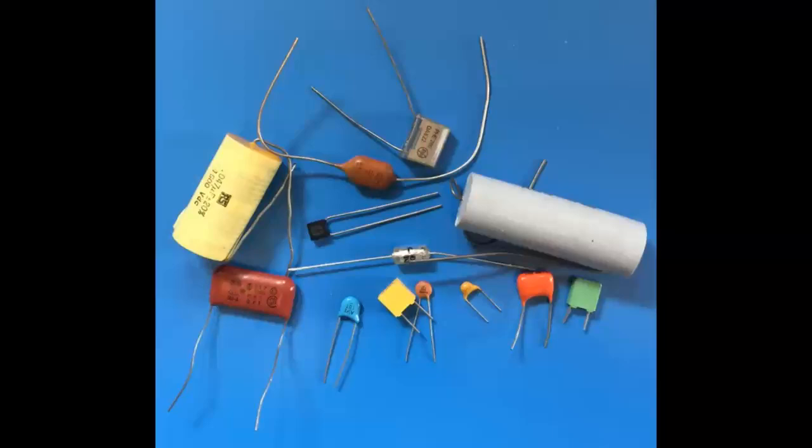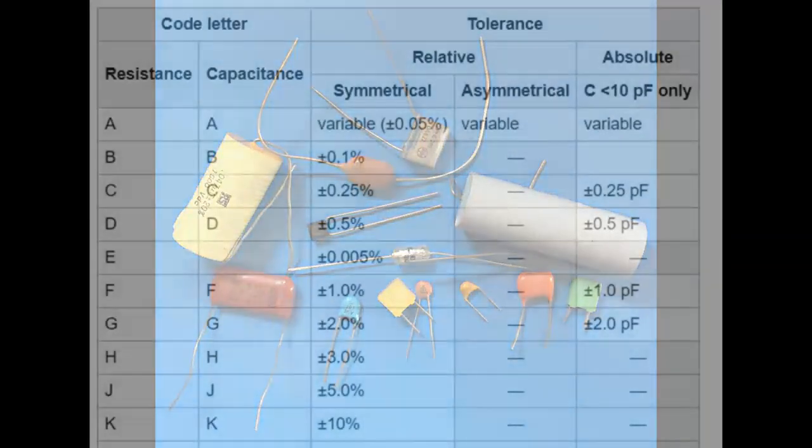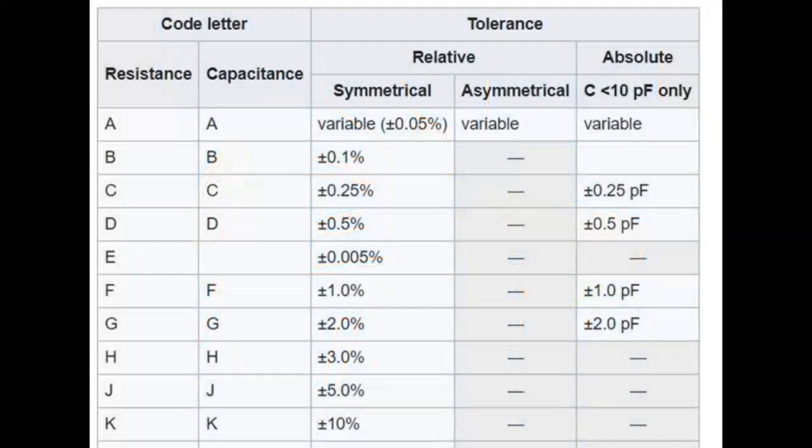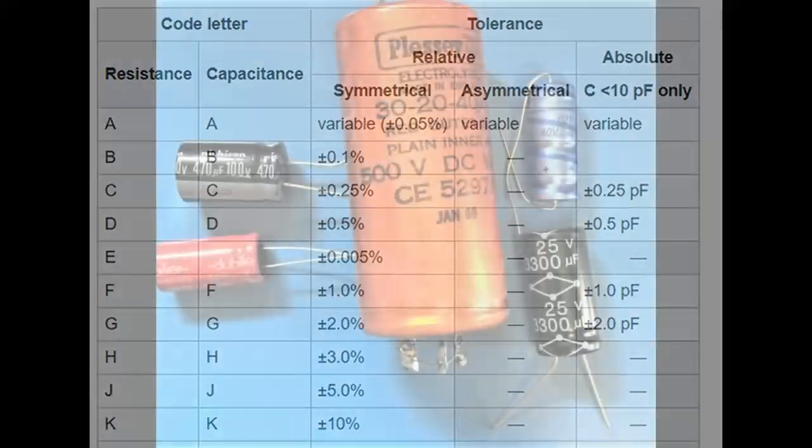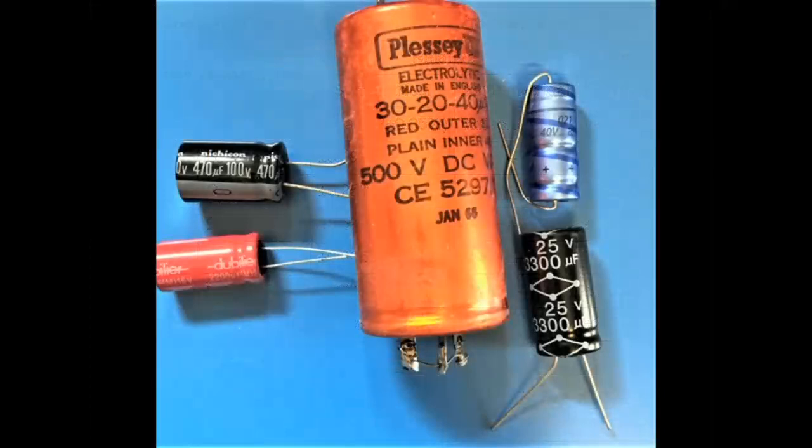There are, as with resistors, tolerances with their capacitance values, and again, unless the circuit calls for precision components, then standard 5% or even 10% will be fine for all other projects. There is, however, a voltage rating, and this must be taken into account when placing a capacitor in a circuit.